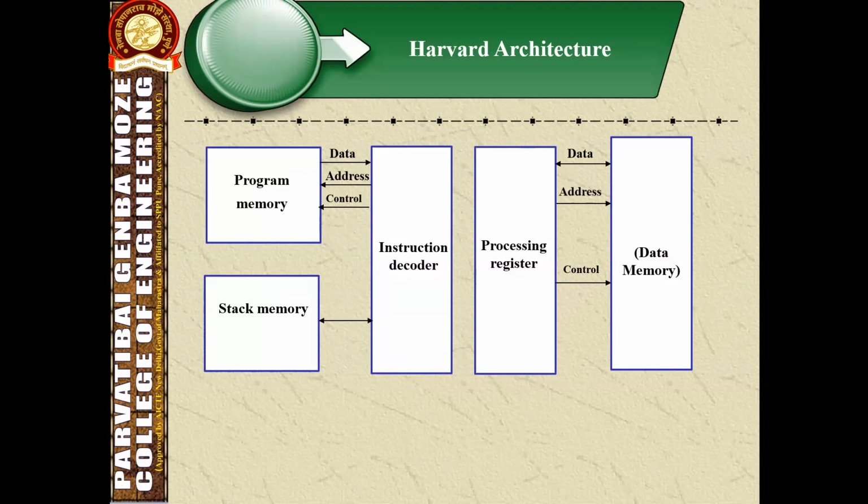A large number of analog to digital converter ICs have been produced by many manufacturers like National Semiconductor, Motorola, etc., to meet various demands such as speed and response, resolution and compatibility, and ease of interfacing with the microprocessor. National Semiconductor produces the analog to digital converter 0809, which is an 8-bit analog to digital converter, whereas Intersil produces IC 7109, which is a 12-bit analog to digital converter.